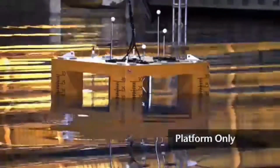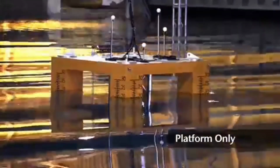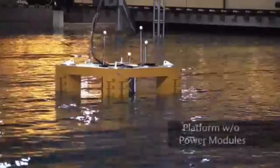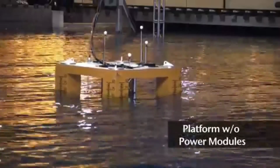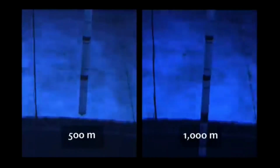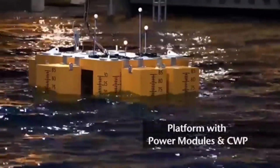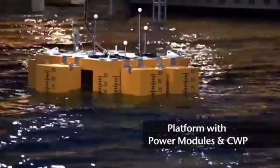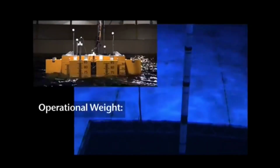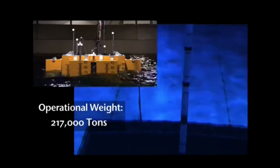The platform by itself, ballasted to include the weight of the pipe fabrication facility. The platform with 6 power modules. The platform in the cold water pipe fabrication phase without power modules, with 2 different pipe lengths of 500 and 1,000 meters. And the platform in the operational mode with 6 power modules and the 1,000-meter CWP. The total full-scale weight of an operational OTEC system and platform is 217,000 tons.